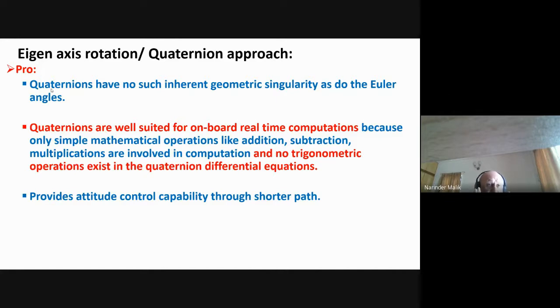Say you are defining the angle of rotation phi, which I mentioned. Now, suppose I want to rotate by 90 degrees, or I can rotate by minus 270 degrees. This method gives me the rotation in the shortest path, that is 90 degrees, instead of minus 270 degrees, or 30 degrees instead of 330 degrees. So it gives me the flexibility of the shortest path approach.